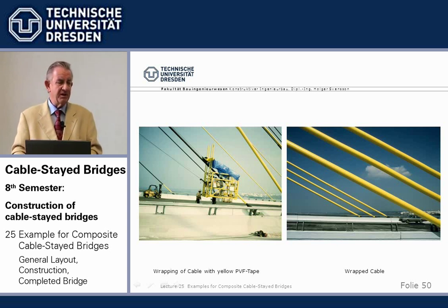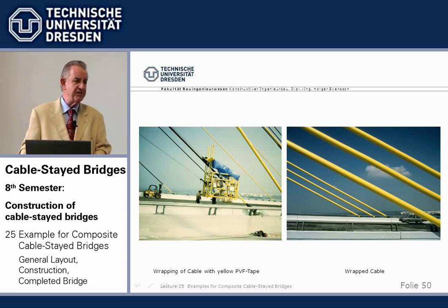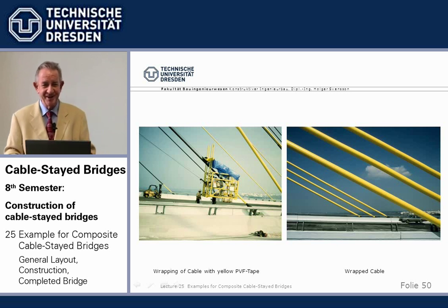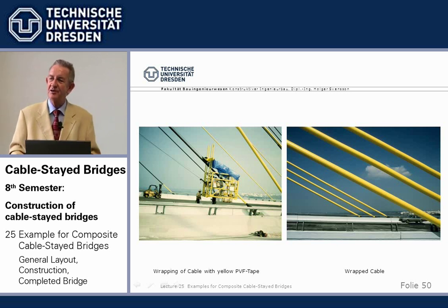Then we need only to find a tape which is UV resistant. PVC is not, as we found out, but we found PVF tape, polyvinyl fluoride, which is UV resistant, nicely colored, brand name Tedlar, and that's what we used and had lots of tests done. So we wrap the cable, and then we sing against the dark blue sky and the intense sun in Texas. That looks very nicely.